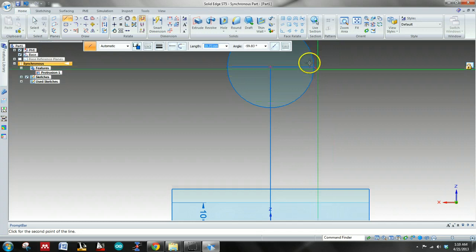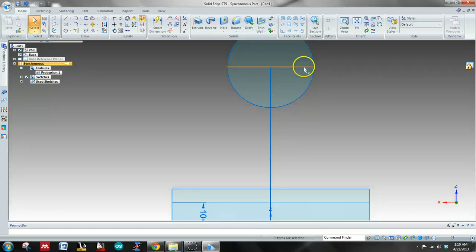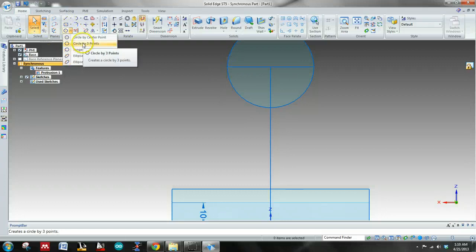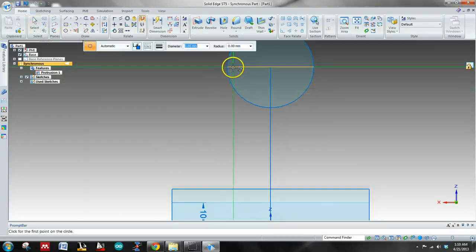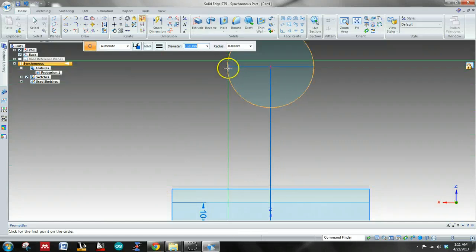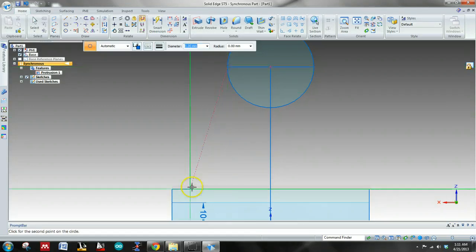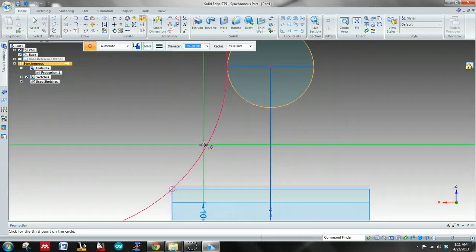These lines that I put here, their only purpose is to serve as a guideline, because I know that this is tangent. We're going to need to put in this arc right here, so I need to know that the point I'm putting it here is exactly tangent. It automatically does this, but this is just a little bit more of a robust way because a lot of people mess this up, so I just want to do it this way. Okay, so diameter 200, enter.